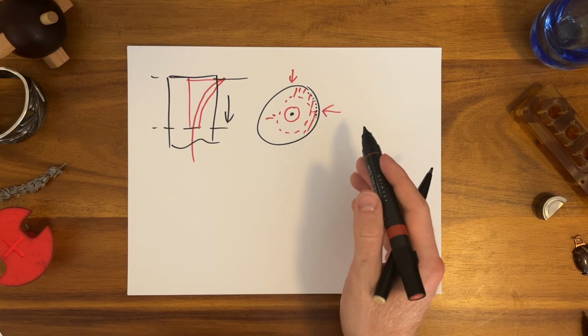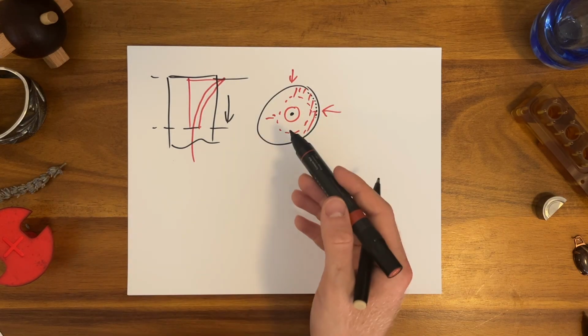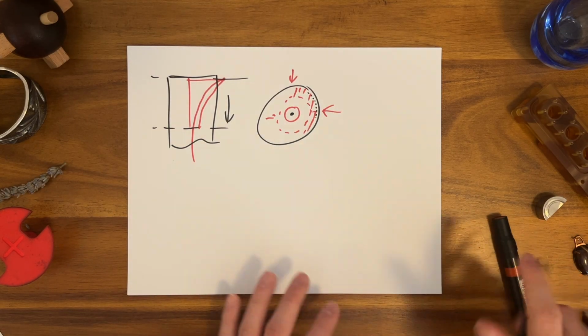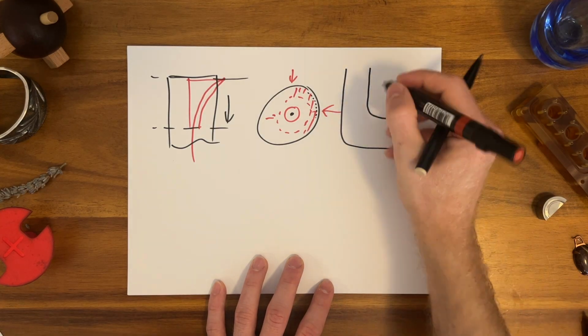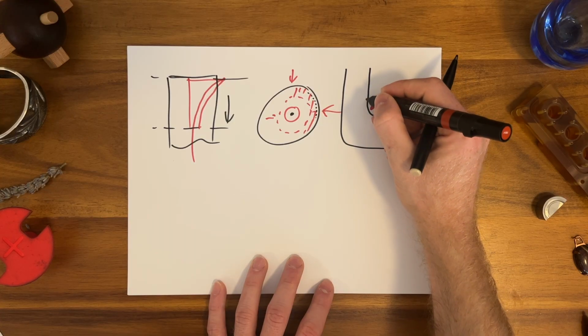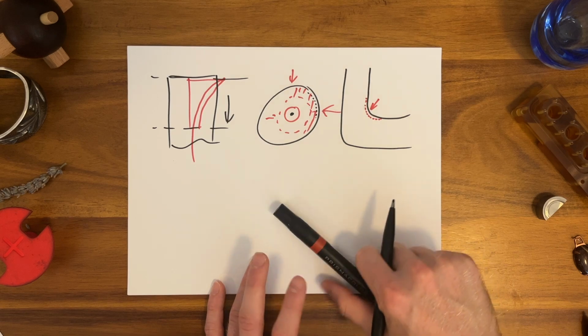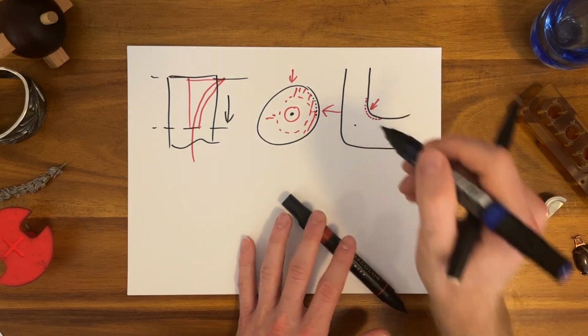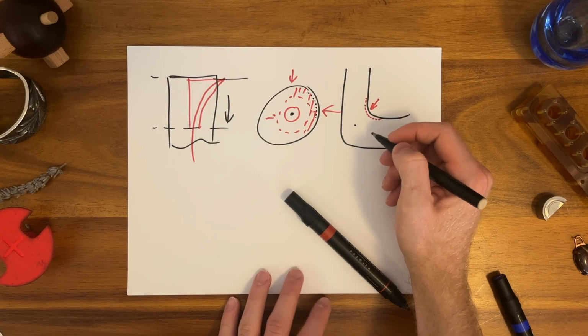So it's going to take less time to heat the center of that cylinder than an equivalently thick planar solid. The inverse is also true. Let's say you're welding on the inside of a corner. You're applying heat here. Well, the first little bit of material, if you're looking at this point here, super high Fourier number, the wave hasn't hit you, nothing's going on.